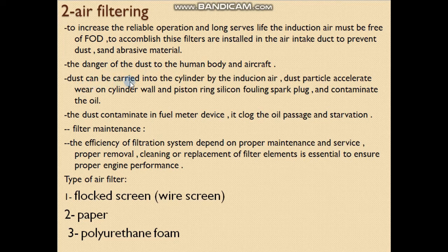Dust can be carried into the cylinder by the induction air. Dust particles accelerate wear on the cylinder wall and piston ring, foul the spark plugs, and contaminate the oil. The dust also contaminates the fuel metering device. It can clog the oil passages and cause oil starvation.